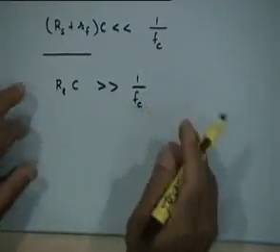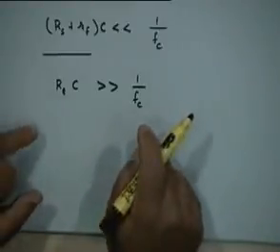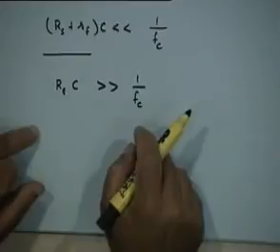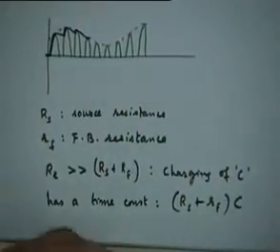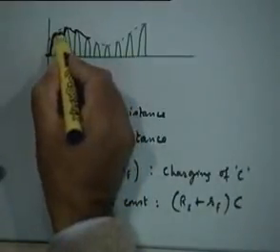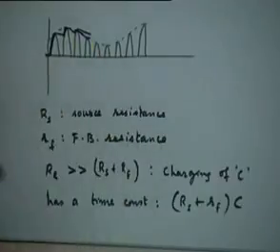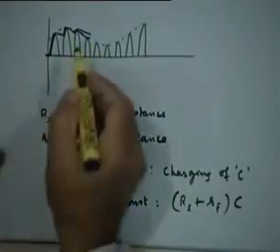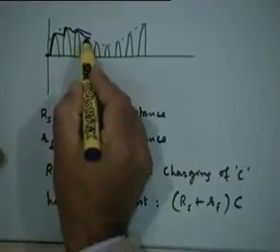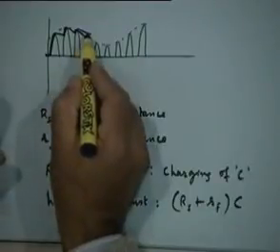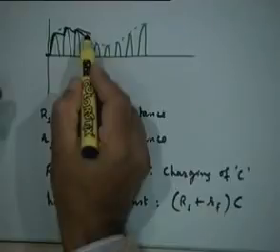But this is one aspect. This can lead to a situation which is not desirable. Do you appreciate that? Let's look at this picture once again. Suppose your discharge time constant is very slow. Let me take a different color now. It can happen that the discharging is very slow. Suppose it is so slow that the next peak comes at a lower value than the amount to which the previous peak has discharged. Right?